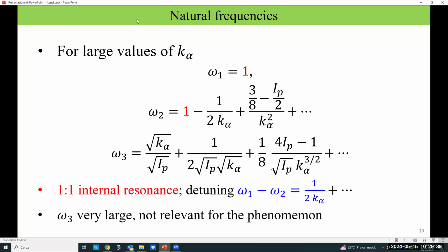So in a typical situation, we have a constant wind speed, which is not a problem. But then there's also the sampling of the wind by the wind turbine blades, which is a function of how fast the blade is rotating, and then the frequency spectrum, which is the turbulent part. So in your analysis, you're taking the turbulent part close to the natural frequency, which is sine omega t. But the natural frequency, because you have nonlinearity, is not a constant. So it's amplitude dependent. It's dependent to a certain extent also on the rotational frequency because of